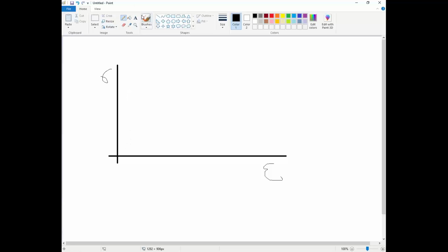First, this is the elastic zone. Beyond this point, the component enters the plastic zone. This is the yield point. Then there is some permanent deformation occurring, and finally you may get the stress strain curve like this. At this point, this will be your tensile strength, sigma T max. This will be your yield strength.